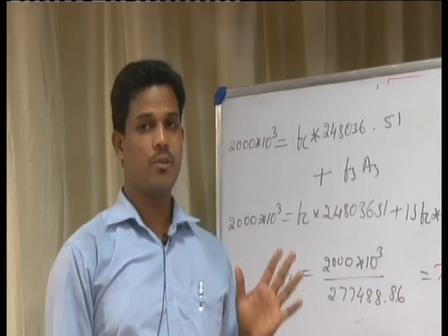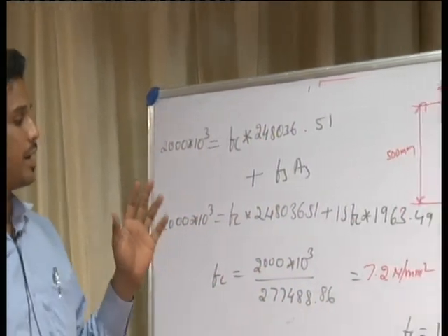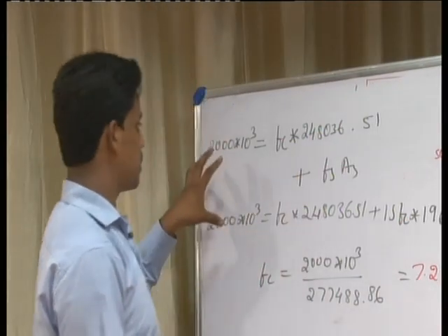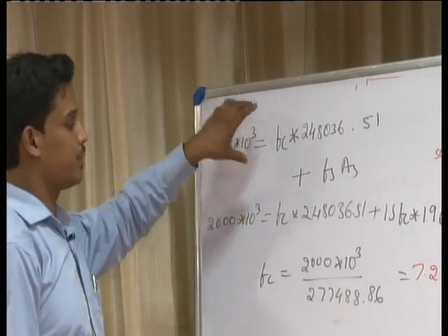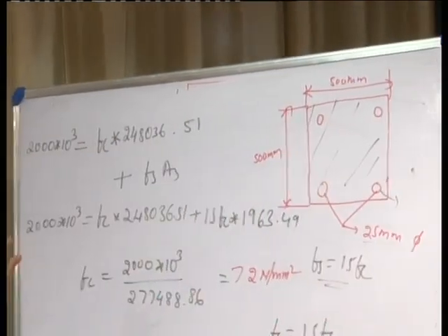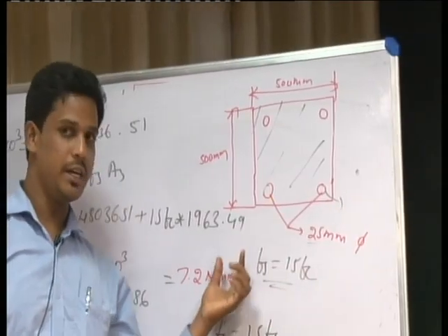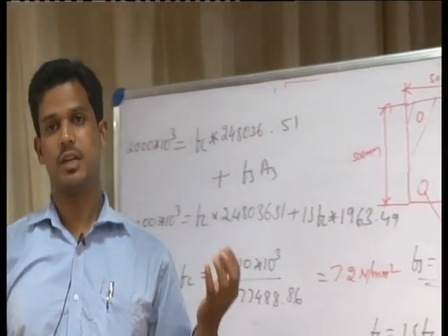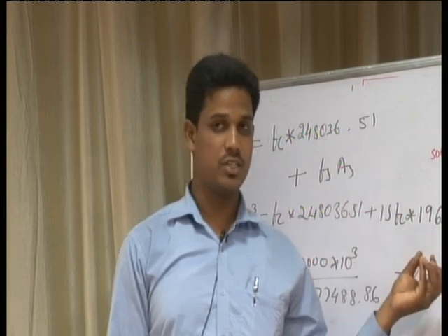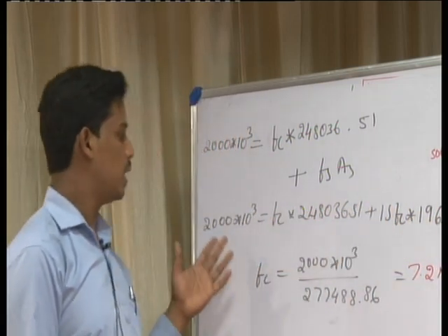In the second step we have calculated the area of concrete. In the third step we have developed an equation, the stress in steel in terms of stress in concrete, and this is substituted in the load equation.